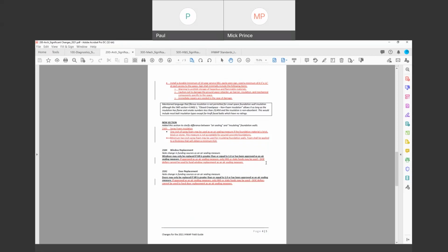A lot of people over the years are just spraying the 1 inch, calling it air sealing, and it's like you're air sealing something that doesn't even allow air to move through. Right. Good point. The poured concrete foundations are pretty tight. But if you're looking at a brick, stone, even concrete block foundation, they can be pretty leaky.